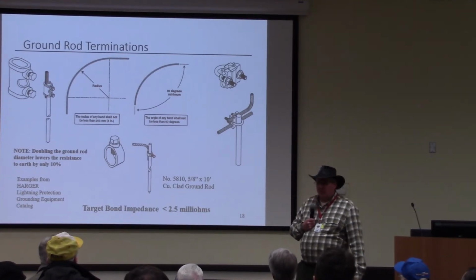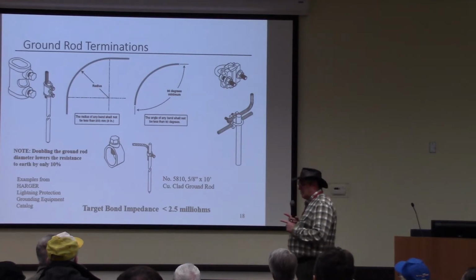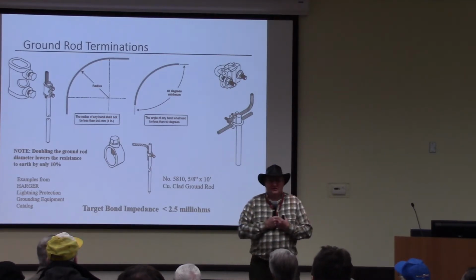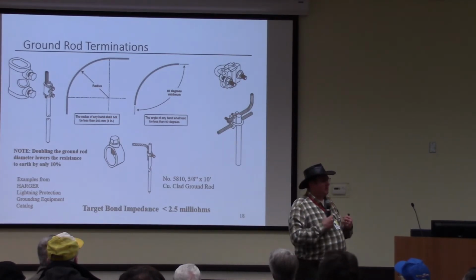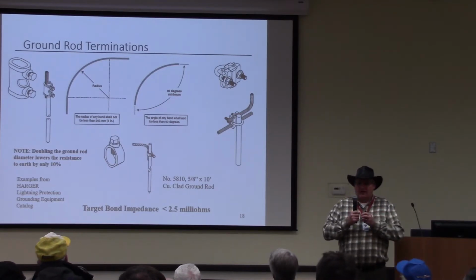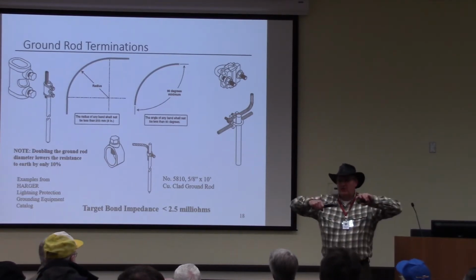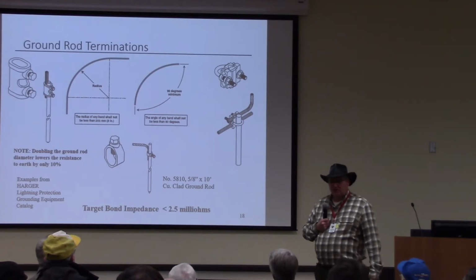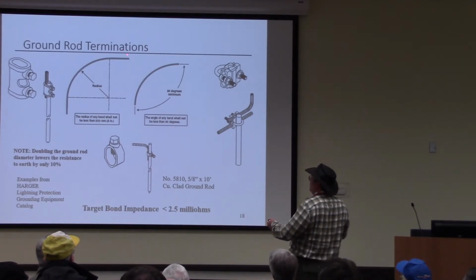Those magnetic fields are going to be such that it's going to try to straighten that wire out. If you have current in 2 wires that's opposite, it's going to try to pull those 2 wires together. When you have current flowing in a single wire in a bend, it's in the same direction and they're going to try to force each other apart. So it's going to try to straighten out that curve.